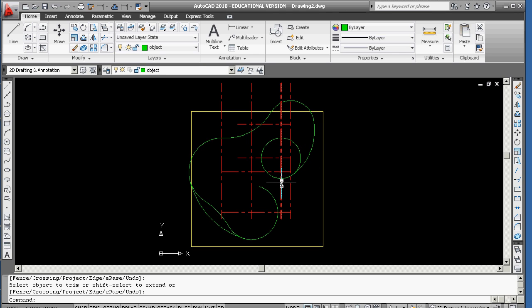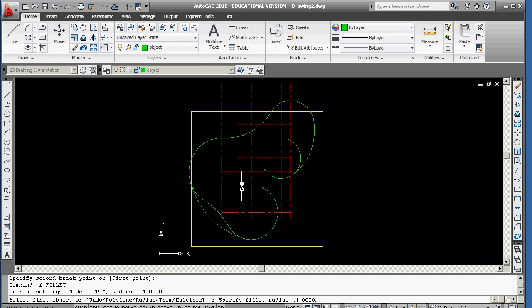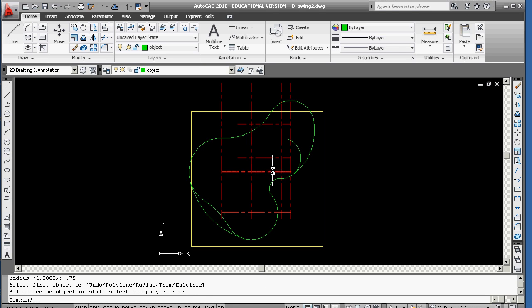This circle comes around and it has a radius of 0.75. Again, these can be filleted. So we can go to here, fillet radius 0.75. Click here, and now I can trim some things out. And you've got this, erase this, trim this. So you've got that base piece.